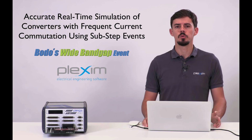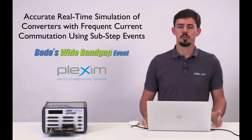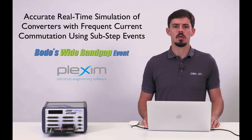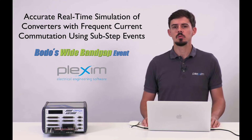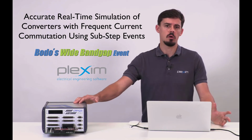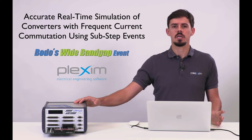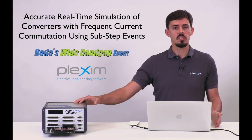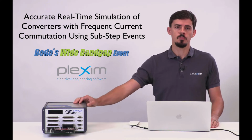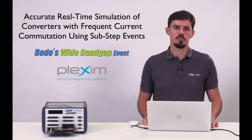Wide-bandgap devices offer the potential to operate at higher temperatures, higher blocking voltages, but also higher switching frequencies compared to their silicon counterparts. And especially the high switching frequencies are a problem when it comes to the real-time simulation of switched power converters. Because there, any switching event will in general not coincide with a fixed model step of the simulator. And this includes natural commutation, but also forced commutation of devices.